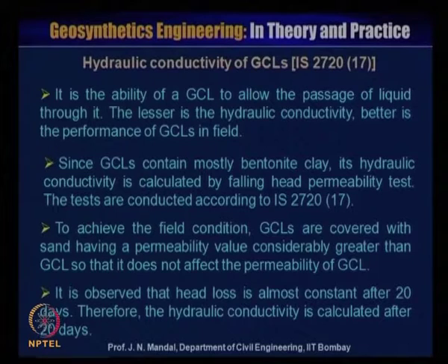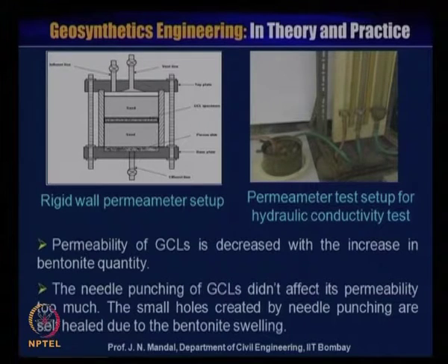It is observed that head loss is almost constant after 20 days. Therefore, the hydraulic conductivity is calculated after 20 days. So, here is the rigid-wall permeameter test setup for the hydraulic conductivity test.